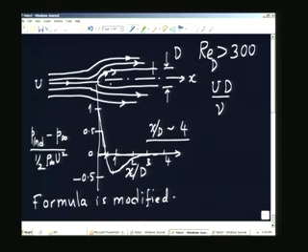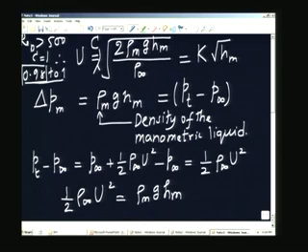This comes from the boundary layer theory, assuming that the boundary layer is very thin, and that is satisfied once you have a Reynolds number based on the diameter greater than about 300. It is going to be thin, and therefore, it is more or less a satisfied requirement. But in order to allow for this small effect of the friction, we can multiply by the factor which I showed in the previous slide. I will introduce a factor C which is between 0.98 and 1 to account for the presence of friction.